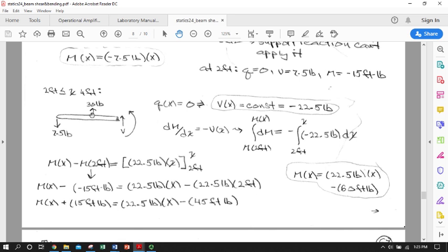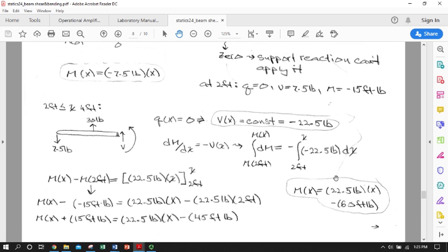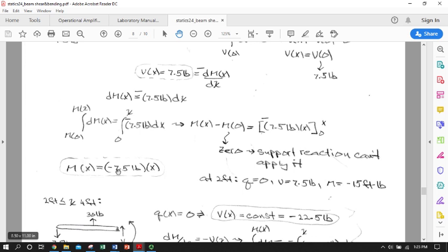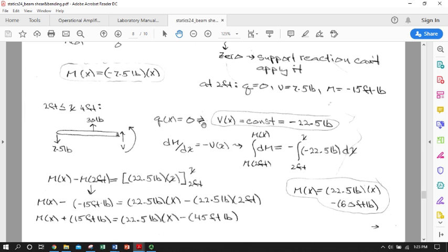So as I pass this point, shear switches. Let's see what happened to moment as I went from one region to another. In my first region, moment had a negative sign, shear had a positive sign, moment was linear with x but headed downward. I passed my 30-pound applied load, my shear took a step function downward, and the slope of my moment equation with x, which is still linear, went from negative to positive, switched.